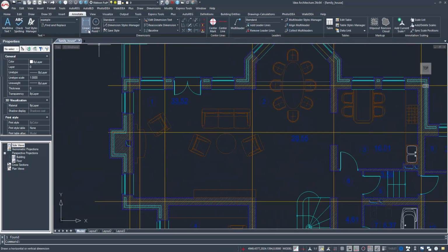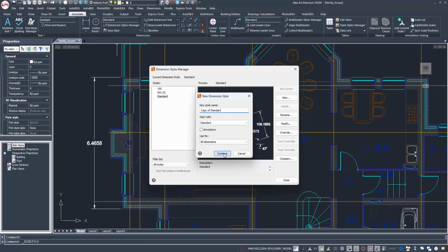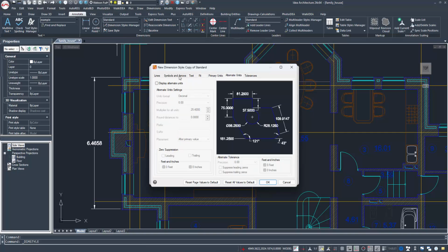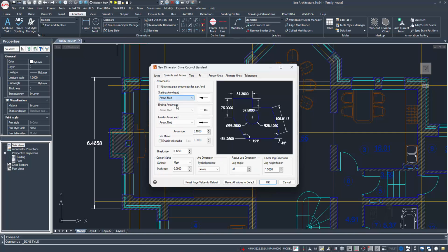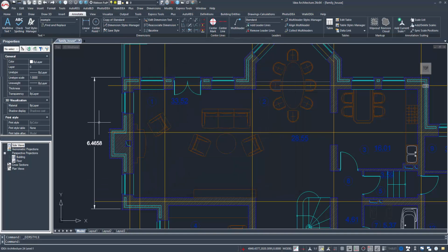Dimensions. The dimensioning tools allow the quick addition of measurements to the drawing. We can create basic types of dimensioning: linear, angular, diametric, radial, and reference. The program designs the current layer using the defined dimensioning style. From the dimensioning style, we can define the text style and the colors of the various components. Also, there is the possibility of creating a new dimensioning style by the user, as well as modifications of an existing one.